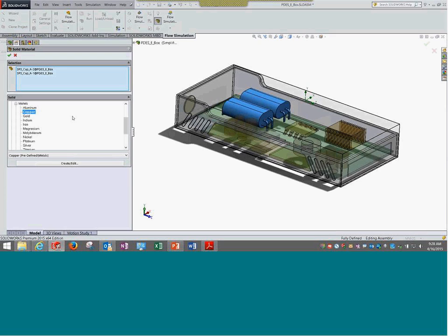It is a very useful option. When there are many components, it is a difficult task to remember and apply those solid materials from simulation one by one. Instead, when you import them from CAD, thereon we can explore it and understand if it has done all good. There could be materials which are customized in CAD that may not be detected, so all those changes can be done. However, at the global level or at a generic level, there is this option, and you can actually import material from SolidWorks CAD to Flow Simulation. Okay, this is what comes.